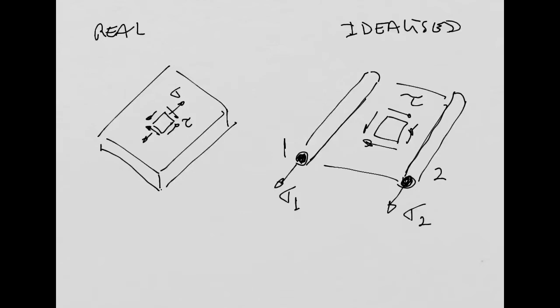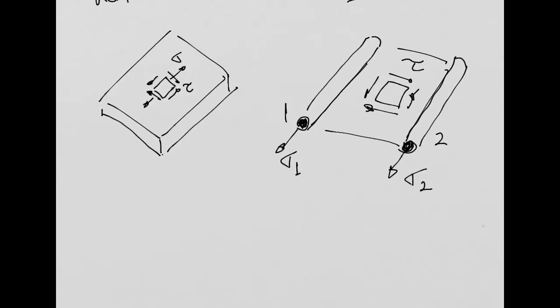So we transformed this into very simple geometry, these booms, which are basically rod elements with circular cross-section. And then last week we learned how to obtain the areas of the booms. For example, this boom 1 will have an area B1, this boom 2 will have an area B2.